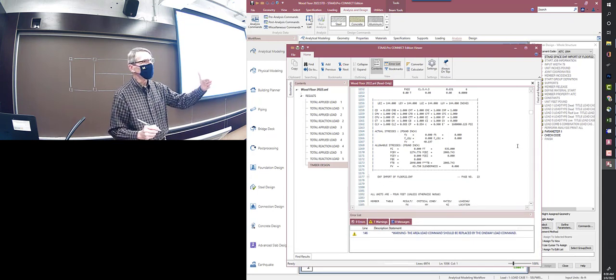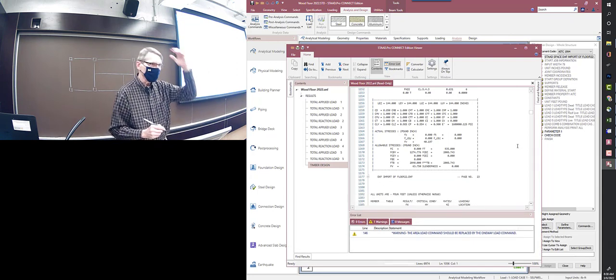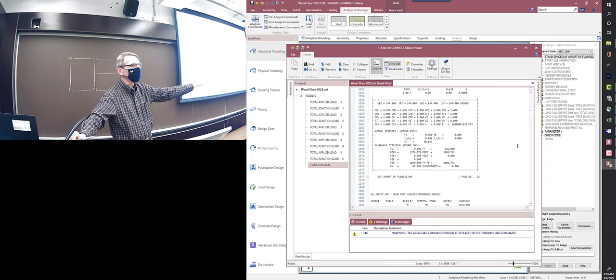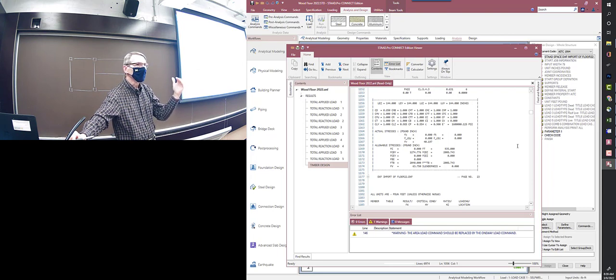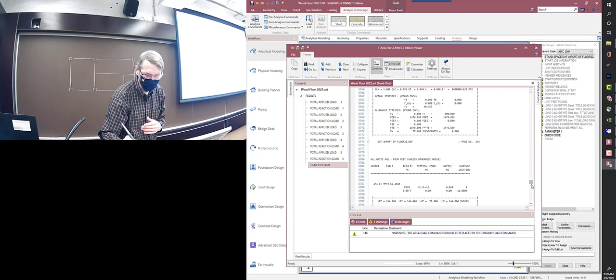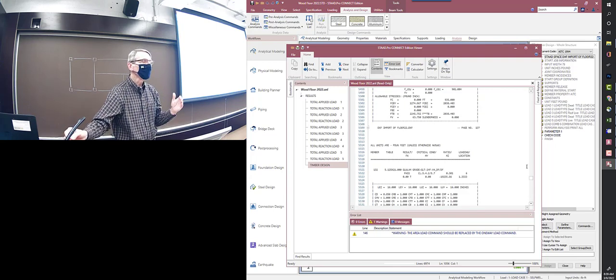member by member, all the members that you do the code check on, and I forget if I set the code check for all the members. I think I did. You probably should. At one point when I was playing with this a week ago, I was thinking, if you set the code check to all the members, you get a ton of results. So I was trying to limit it to maybe only the critical members.